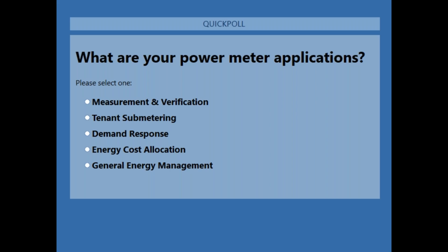And then there's a scaling factor that we have in the meter itself. So, for example, if you had 2400 volts coming in instead of 600, you would step that down to 600 and then apply a 4-to-1 factor, so the meter can understand what the voltage is that it's reading, and then manage the input voltage correctly.